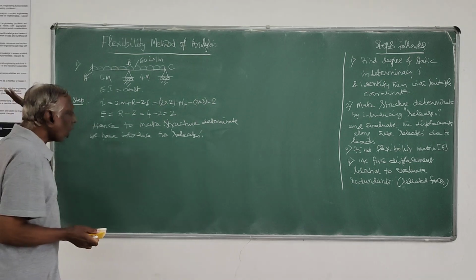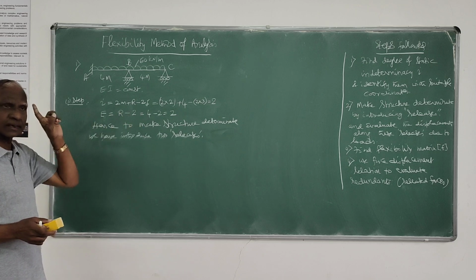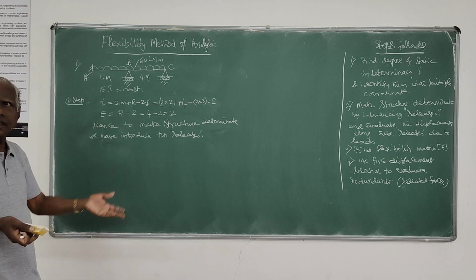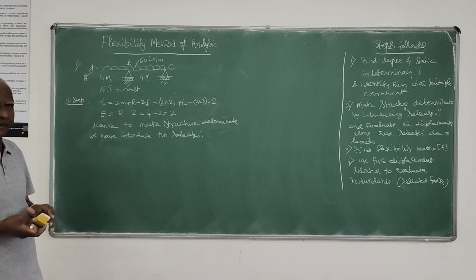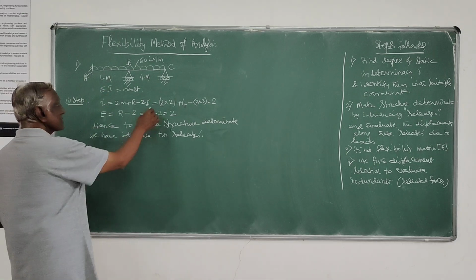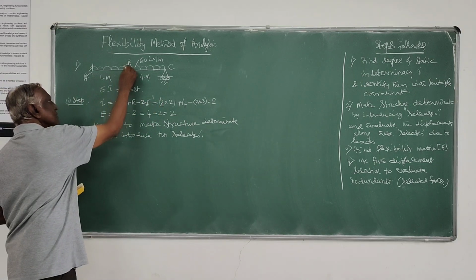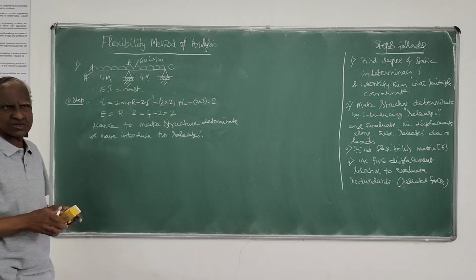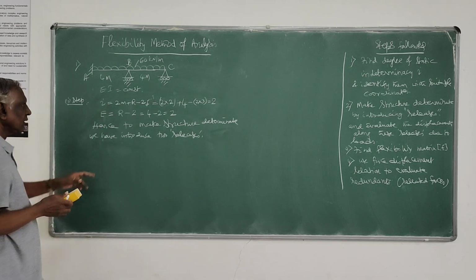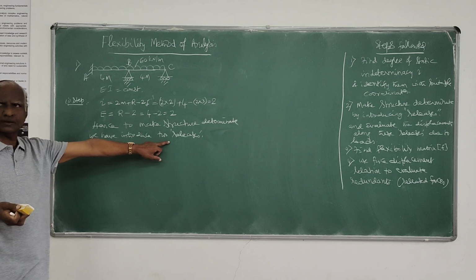So in general, all beams and single story rigid frames are only externally indeterminate. It's a rule you can always remember: only external reactions you can remove in order to make it determinate. And also, of course, some imposed boundary conditions you can use, because the formula has minus imposed conditions. We can also introduce some internal hinges in order to make it determinate. So there are various possible ways of making the structure determinate by introducing the 2 releases.